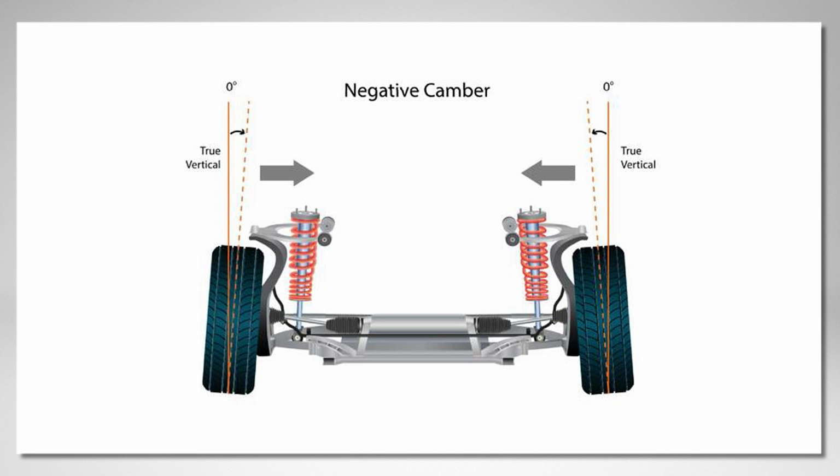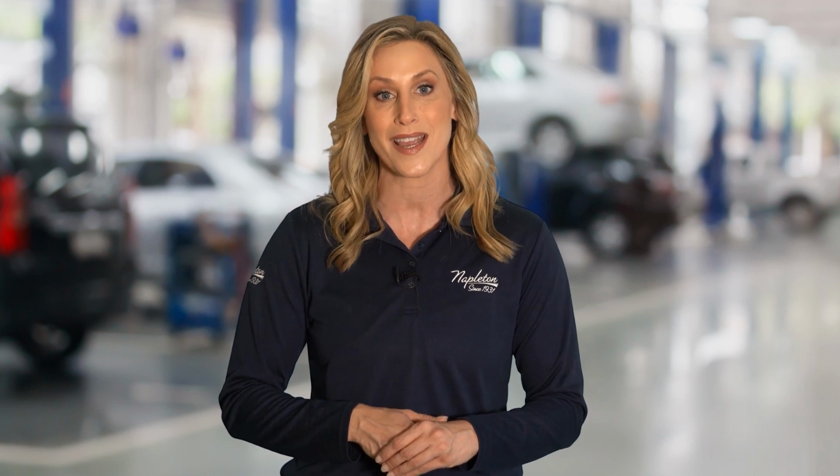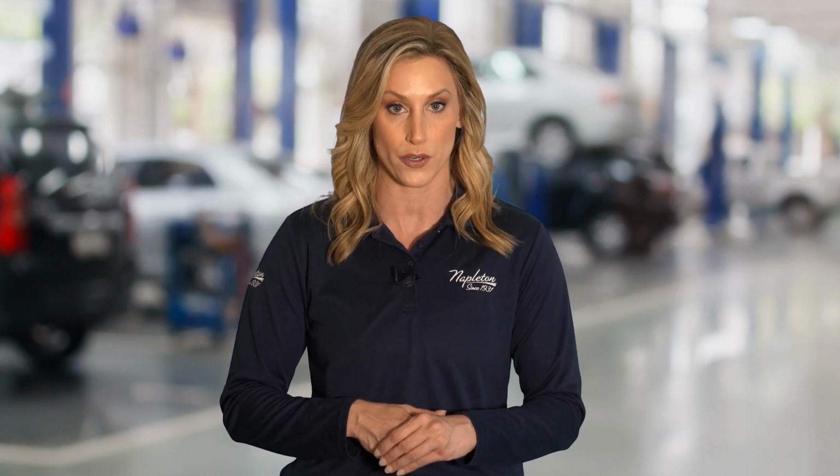A small amount of negative camber at the rear improves cornering performance by applying maximum tread to the road surface. Solid rear axle design operates with zero camber. Any significant camber or toe reading with this style of suspension may indicate bent or damaged componentry.